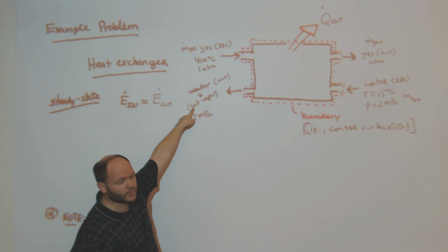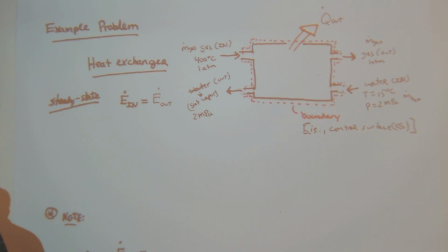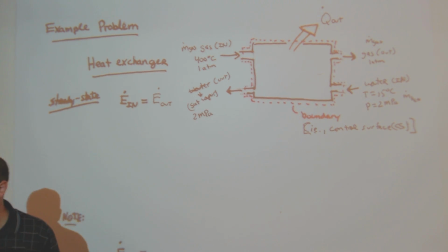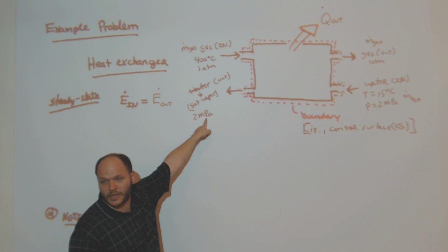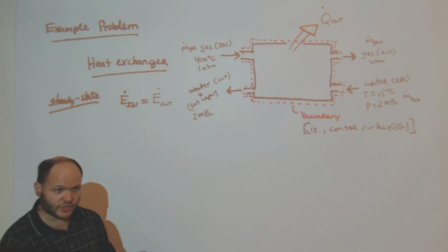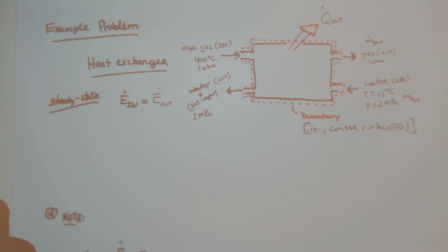So let's just make a guess. What do you think the temperature of my water vapor leaving is? What's that? Above 100 C. Why do you say above 100 C? Okay, so what is the pressure associated with saturated vapor, in pascals at 1 atmosphere, what we're at right now? So 1 atmosphere is the same as 101 kilopascals, 101.3 something, right? Kilopascals. Now we have pressurized. So as I pressurize a vapor, what happens to its saturation temperature? It goes up.